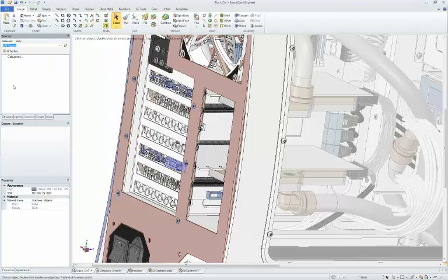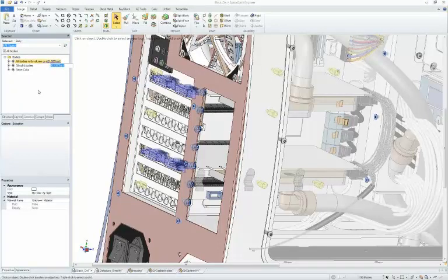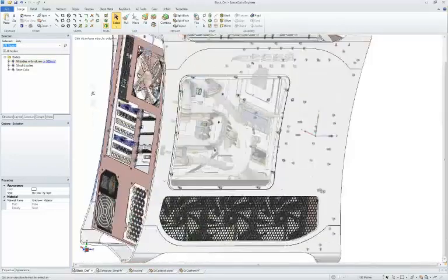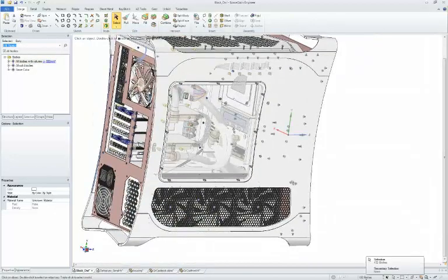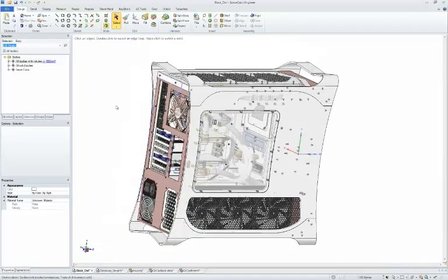And the common thing that I search for is, I usually search for area. So you can search for a given area. I can say, actually everything that's below 500 cubic millimeters or inches, depending on how you want to work or operate. But now notice it's found 432 bodies. If I hide everything, you'll see it better.